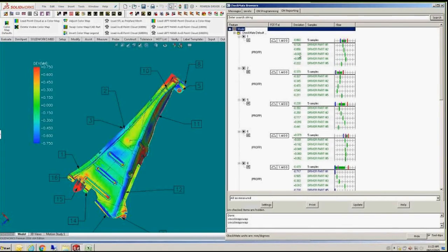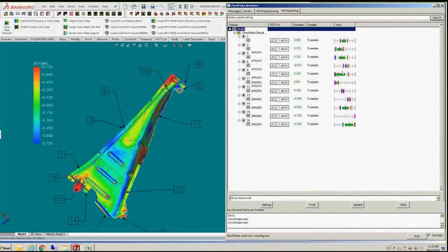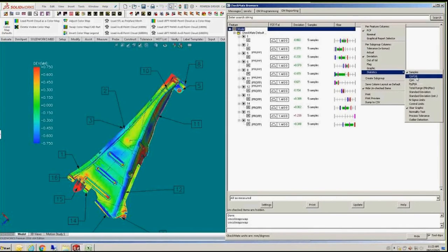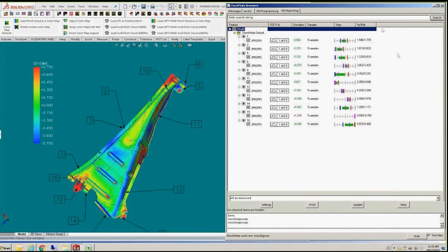You can see we have the 5 samples, driver part 1 through 5. And you can see the individual data. I can go and turn off these, and now we're just looking at the average of each of these samples for these points. Now you can see again, this is customizable. It's like an X-bar chart. For example, in the top one here, the magenta is the mean, the red and the blue are the control limits. It's kind of like looking at a histogram straight down.